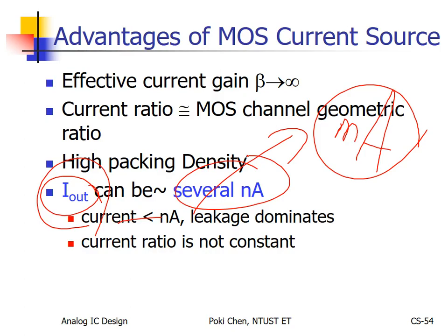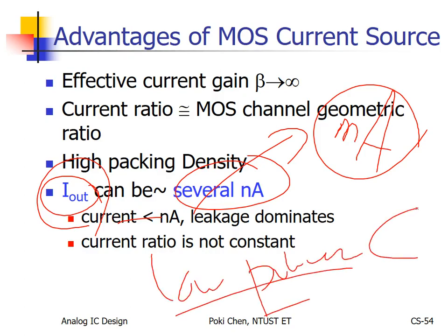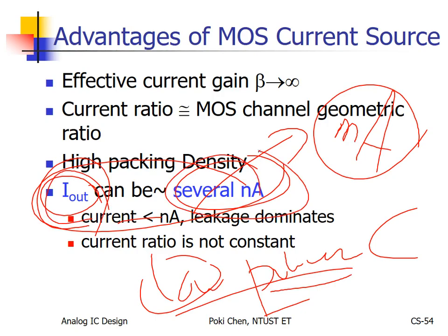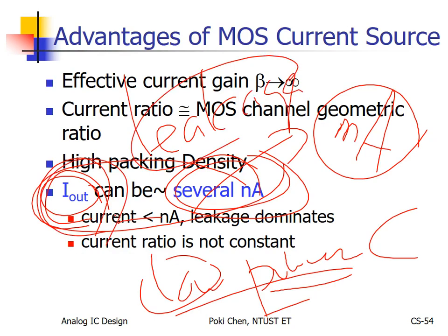Okay, that is the key for very low power circuit design. It's really hard for you with bias voltage to control such extremely low power consumption. But for bias current, piece of cake, we can make the output in such a region. Never mind if they operate in weak inversion, strong inversion, or even with leakage current. Okay, it is totally possible to make the power consumption really, really small.